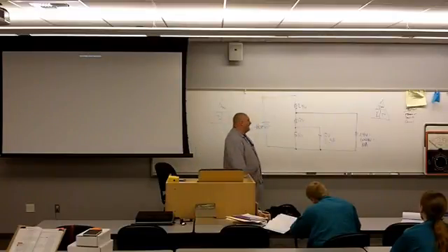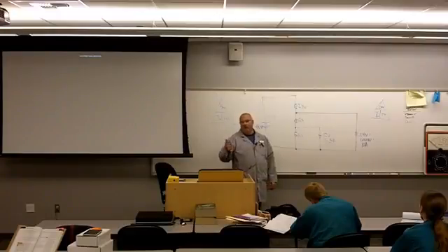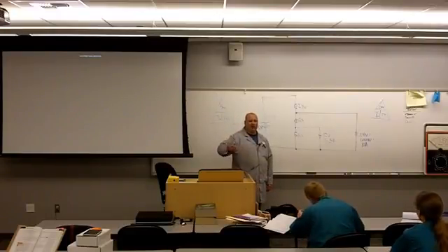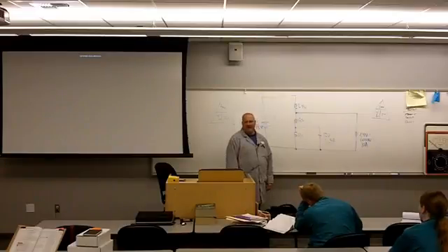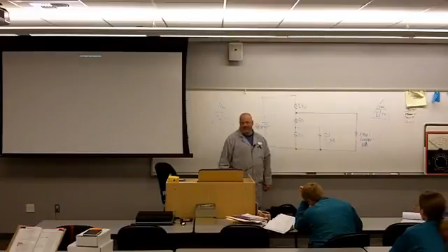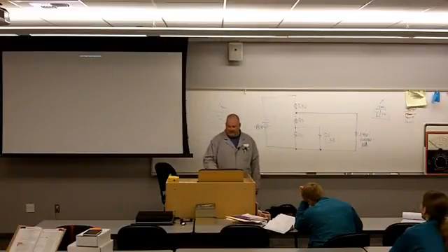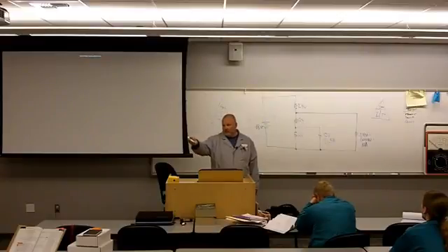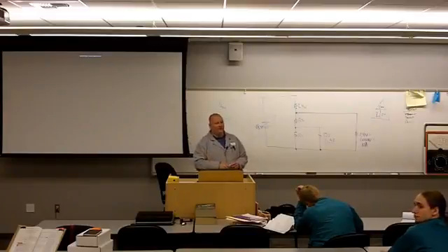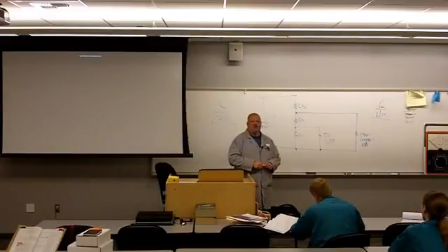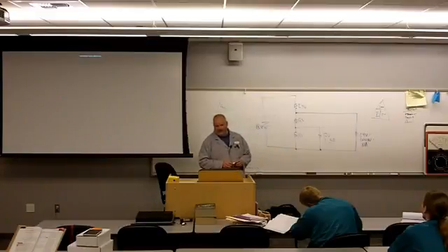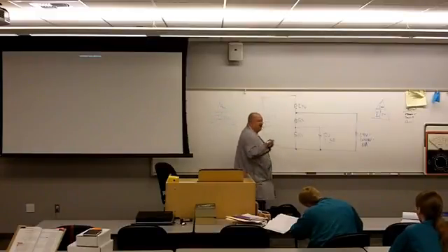Okay. So I said the thumb rule is that the bleeder current is 1/10 of the total load current. What's 1/10 of 10.5? So 10.5 divided by 10, 1/10, is 1.05 amps. Do you all agree with that? I'm getting some puzzled looks. 1/10 of my total load, 1/10 of 10.5 is 1.05. Agree with that? So that's how much current.